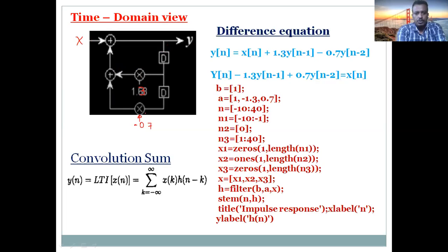These are three basic components, elements of a discrete time system. Okay, so the output here is applied to the delay element. So here we'll have y of n, delay means n minus 1, delayed by 1 unit. So this delayed output, here is a multiplier, multiplied by how much? By 1.3. So at this point, we'll have 1.3, the multiplier constant, times y n minus 1.